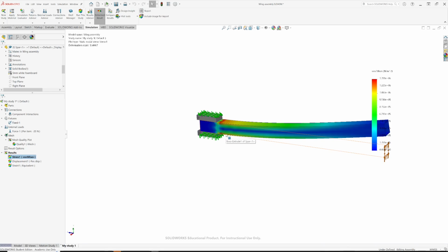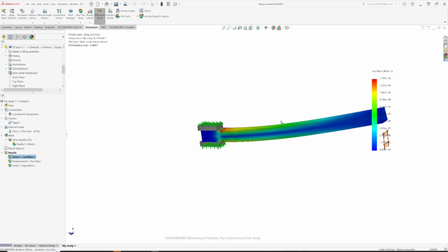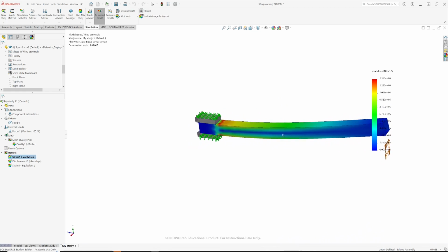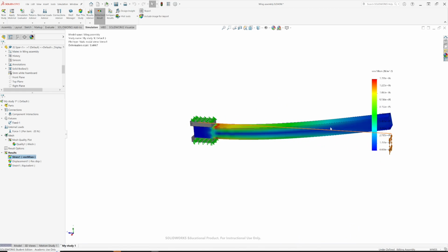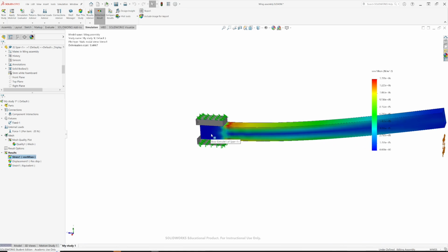And if you recall back to the giant foam board aircraft stuff, looking at conceptual design, the whole principle of the design of that aircraft to minimise the spar mass is that it's kind of a triangle cut out of the middle of the spar. So you just have material where you need it. Inside the vise itself, it's all blue because all the load is being taken by the steel, which is like 200 or 300 times stiffer and stronger than the foam board.